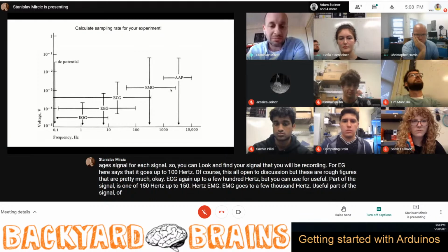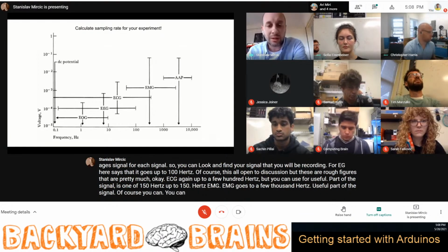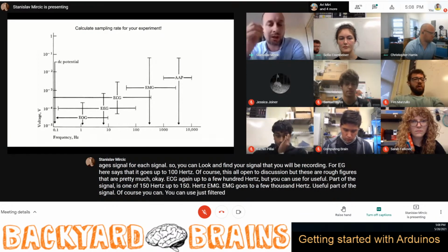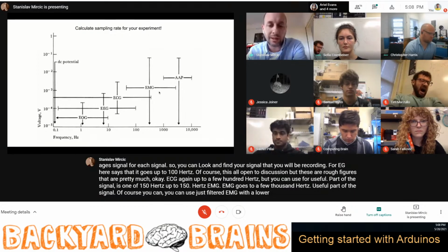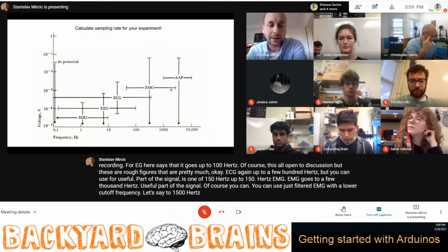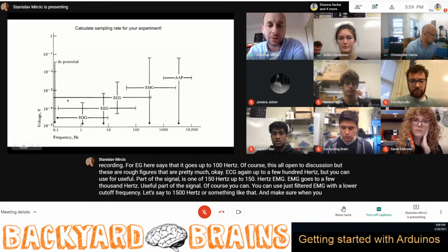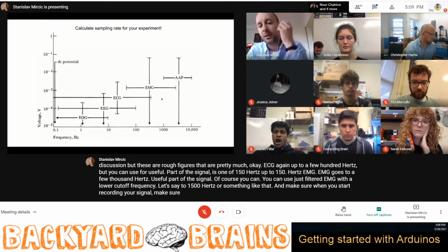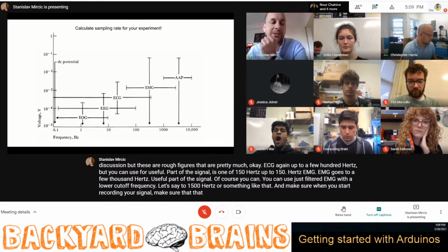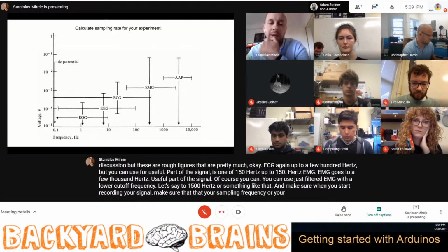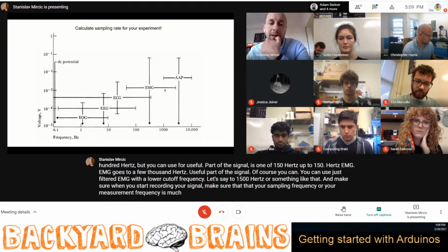Of course, you can use just filtered EMG with a lower cutoff frequency, let's say 1500 hertz or something like that. And when you start recording your signal, make sure that your sampling frequency, or measurement frequency, is much higher than the highest frequency in your signal.